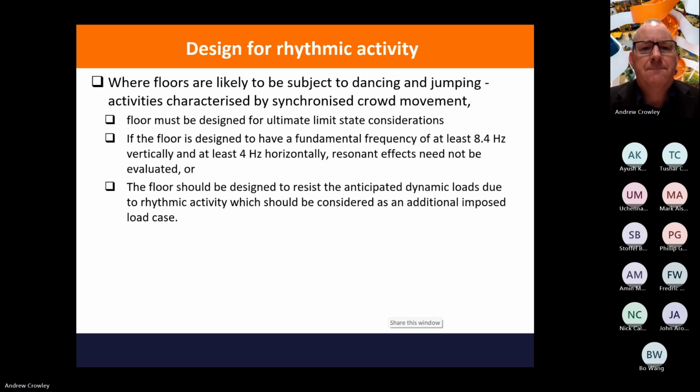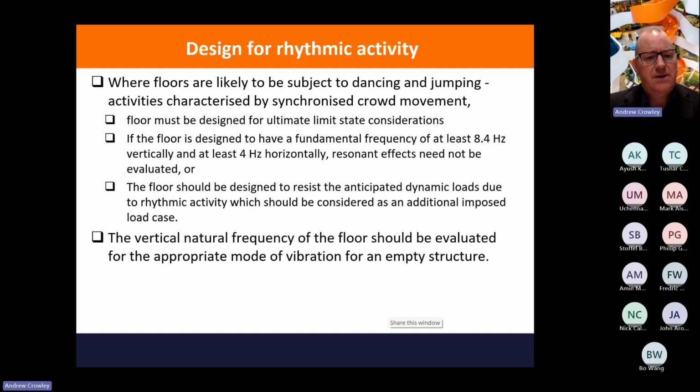However, you can also design the floor to resist the anticipated dynamic loads due to these rhythmic activities, and you consider them to be an imposed load case. So the vertical natural frequency of the floor should be evaluated for the appropriate mode of vibration for an empty structure.